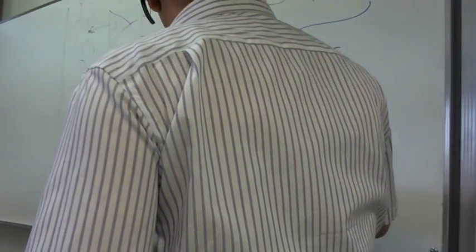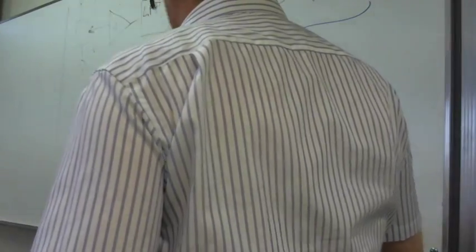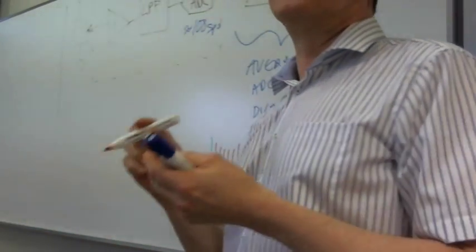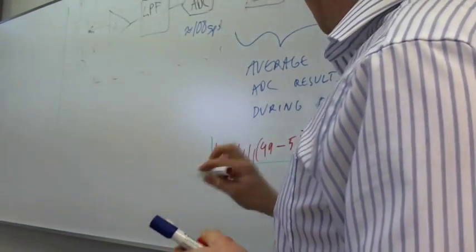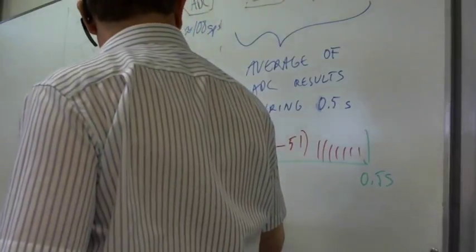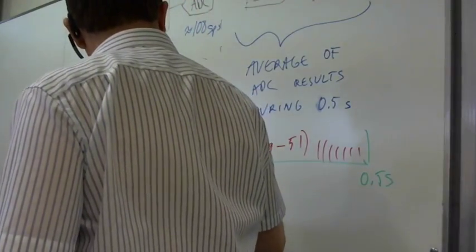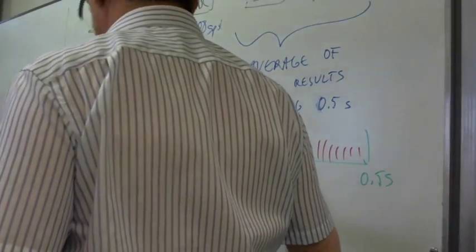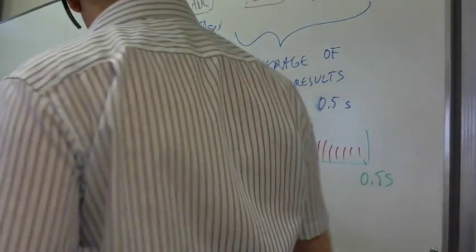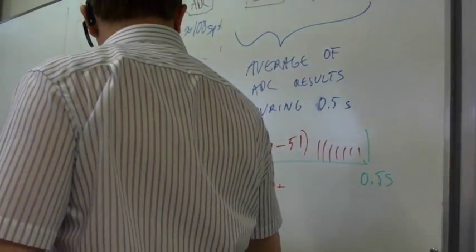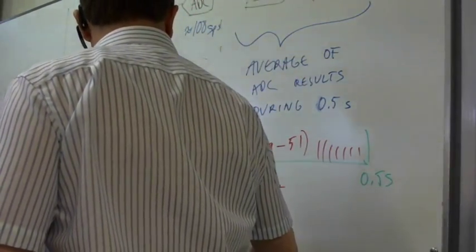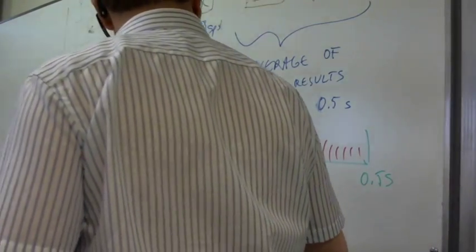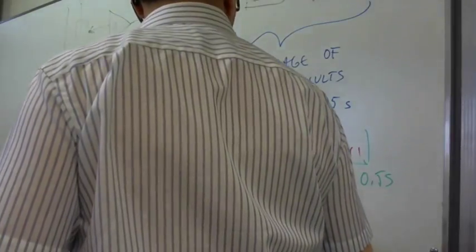So anything between 49 to 51 samples here, which means that in your software you need to have a sample count value that you will increment, and then you would have the ADC sum that you will increment by the ADC value.